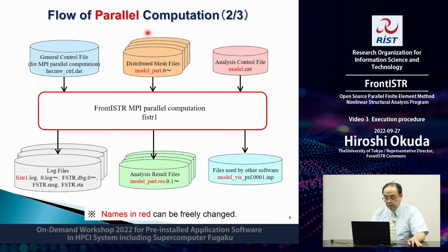Once you obtain the distributed mesh files like this, mostly the same process as the sequential computation is carried out. That is to say, you need to prepare the general control file, the distributed mesh files, and the analysis control files.